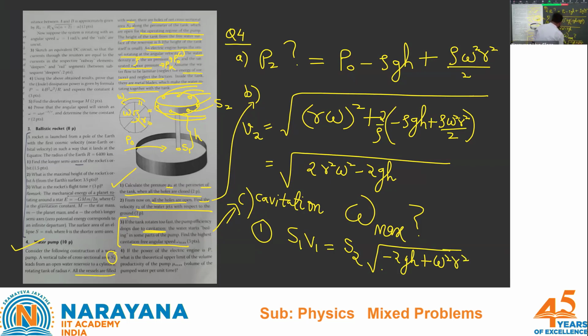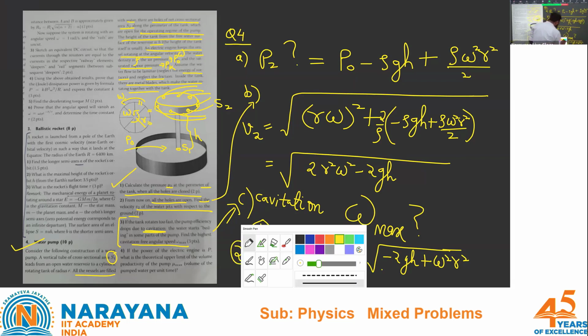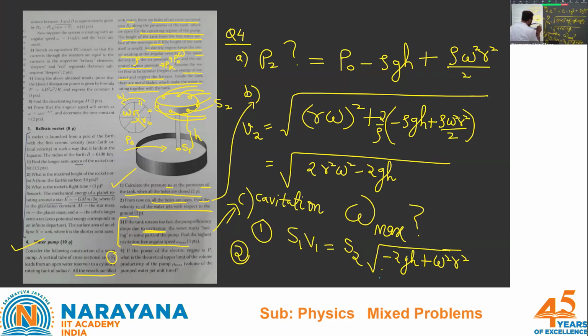It works. This seems to be the first equation. Check. Seems like S1 V1 is equal to S2 into root of omega square r square minus 2gh. That is good enough, first. Secondly, from the top surface, now I want to write one equation from Bernoulli's, that is from the top surface